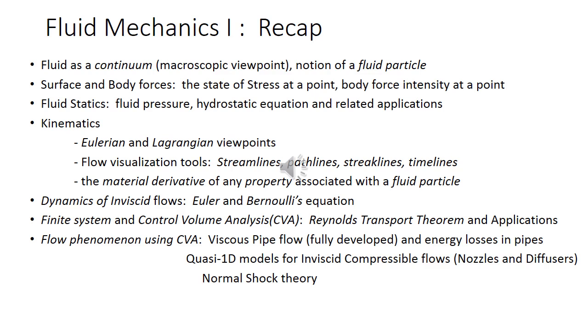Then the surroundings would exert some forces, and those can be easily computed using this approach. But remember, a finite control volume analysis approach requires knowledge of velocity and various fluid properties on the control surface and inside. So it assumes that you know these values, but these values are only known if you perform a detailed fluid flow analysis to obtain information about this, which is what we would be learning in this particular course. What governs the detailed flow behavior, in a nutshell. So this is important from the point of view of connecting what we already know and what we are about to learn.